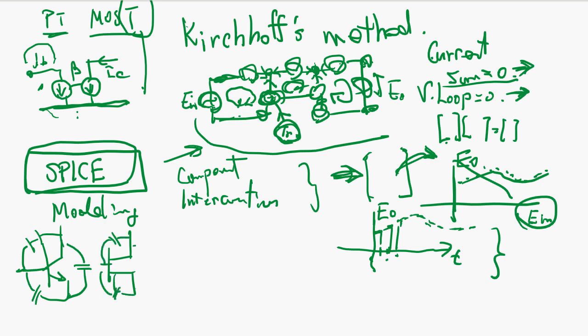And also there is an internal resistance, very small, but internal resistance. So the model is going to have that, and also the characteristics like the bipolar transistor beta, and for the MOS, W and L, with other temperature parameters.